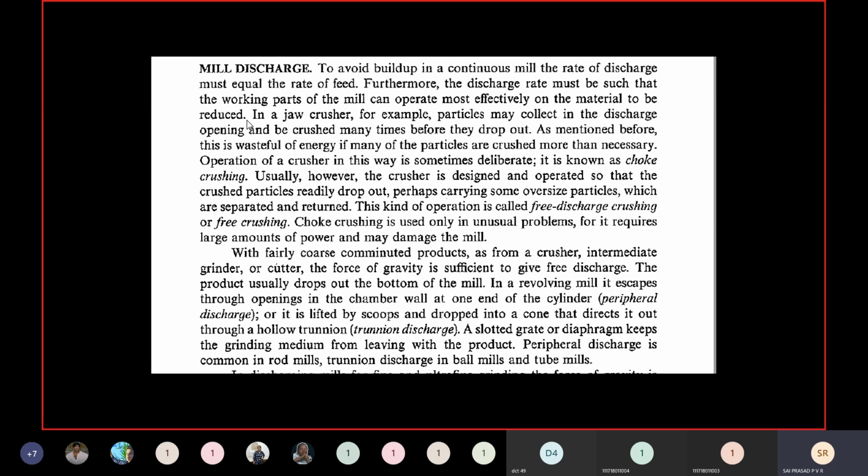As it is coming down, the V shape ensures that the particles again catch each other and crushing takes place. If not, the particle will stay there, take the next blow, and then size reduction takes place. Suppose in that case also it is more, then what will happen? In the case of a gyratory crusher, we have a rotating crushing head on the shaft. Apart from compression, shear forces will also be applied and then size reduction takes place. So it all depends upon the design of the machine, which ensures that at some point or other, forces will be applied by the machine on the object before it goes out of the system. That is the concept of design.